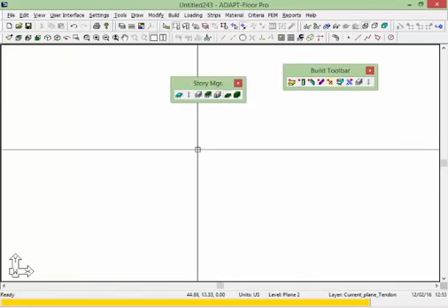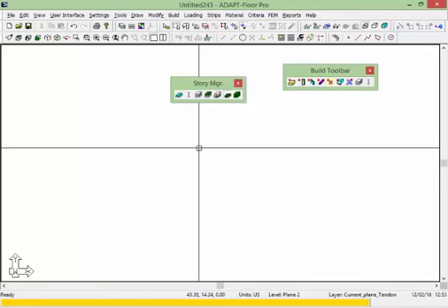So one of the main and most important factors that needs to be used when you're modeling a frame is that columns and beams need to align at their centroids. So when we use a slab, we can actually connect different components through the shell elements, through node shifting and offsetting. But when we have a pure skeletal frame, we want to make sure that we're connecting everything together.